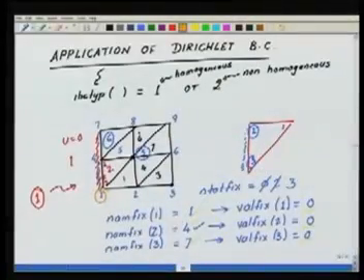It is not the same as what we had in the 1D case, where at most 2 elements participated in the equations for a node. Here we could have, depending on the mesh, many more elements present. Another thing, if I look at this degree of freedom 1, if you remember, this degree of freedom actually participates in the definition of u along this edge, along the boundary edge 2, as well as along the boundary edge 1. Okay.